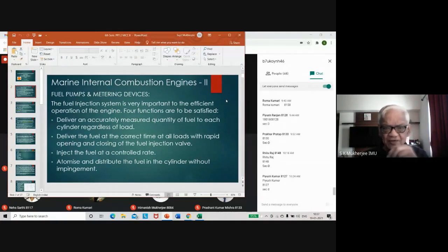When the fuel comes into the combustion chamber, it does not ignite instantaneously. There is a delay. During this delay period, some more oil keeps coming in. And when the combustion actually starts, the entire mass of fuel that has come in combusts. But the fuel coming in is still in process. So when the combustion takes place of the oncoming fuel, the oncoming fuel does not have any more ignition delay.